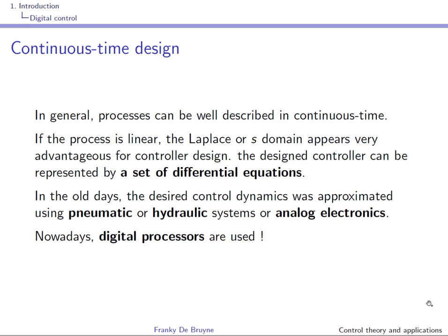We have seen in the course Signals and Systems that processes can be well described in continuous time using differential equations, and when going to the Laplace domain, this gives rise to the concept of a transfer function. If the process is linear, the Laplace or S domain is also advantageous for controller design.